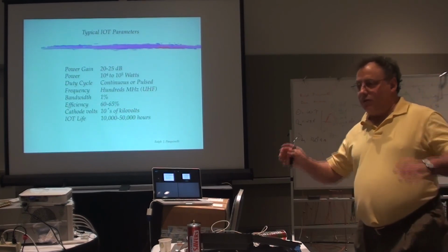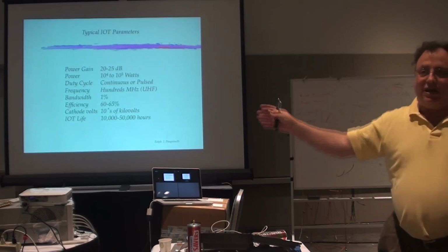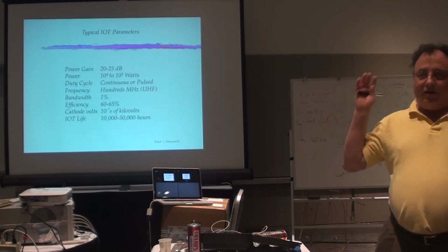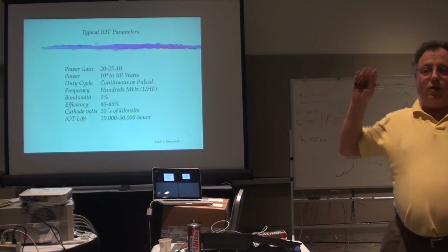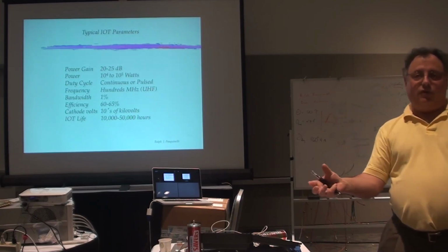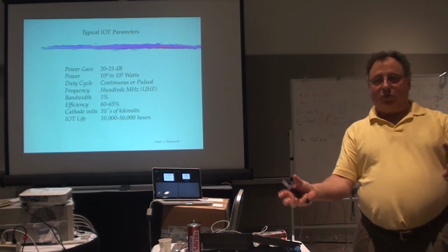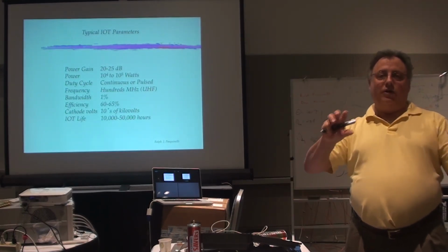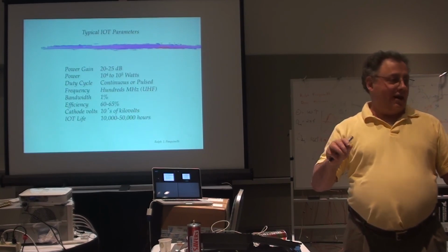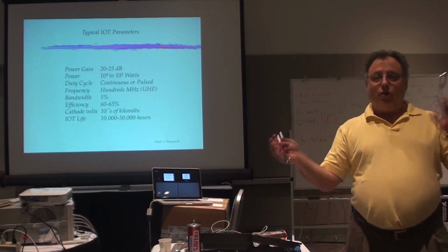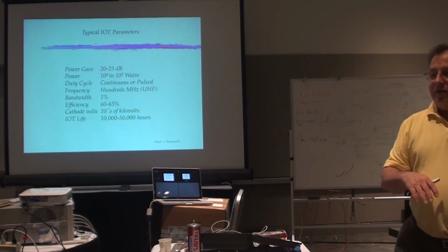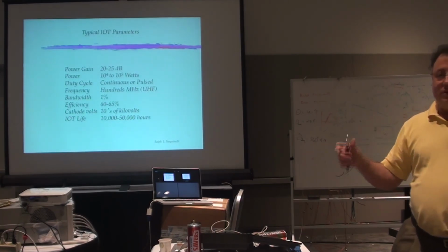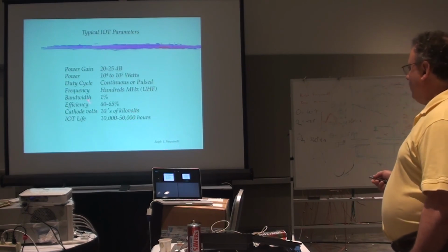You never want to turn a klystron off because it has thermal characteristics. So even when we're not running beam, we have that thing firing all the time. If we're going to be off for a long period of time, you'll turn the filament from red heat, which is what we really call it, down to black heat. So you turn the juice down just enough so the thing's not glowing red hot, because they really are glowing red hot, and it doesn't boil off as many electrons. But you don't want this thing to go from hot to cold, because that thermal cycling is potentially going to break the tube. So they're always on. But you can turn it on and off, and it has a higher efficiency.